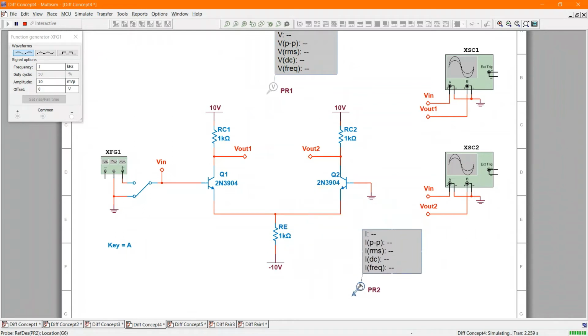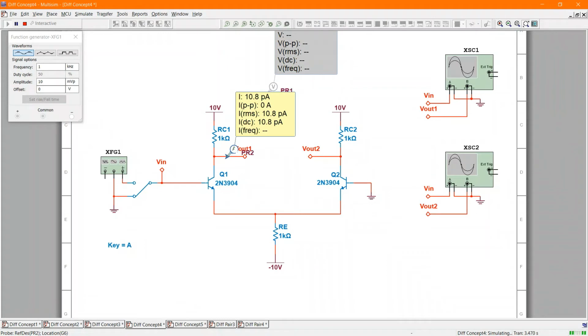Well, how's it going to split that up? I've got both of these transistors. The bases are grounded, and they're on the same piece of silicon. When they make these, they put these transistors all on the same piece of silicon, so the characteristics are virtually identical. How do you think these transistors are going to split up that 9.3 milliamps? And the answer to that is that they should split them fairly equally.